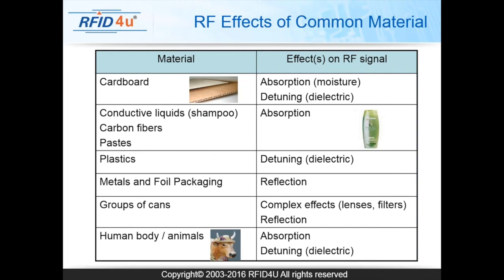And part of what you'll see with UHF is different antenna designs on the inlay itself. Those antenna designs and the design of the chip are built to accommodate some specific material to which they should be attached. So when you're looking for tags, you have to tell your vendors what materials they're going to be attached to so that they can come up with the correct tag or inlay with the correct antenna design.